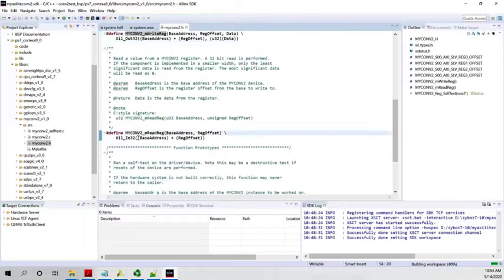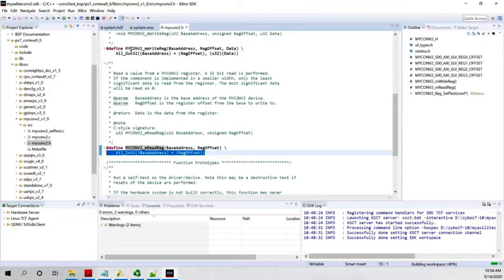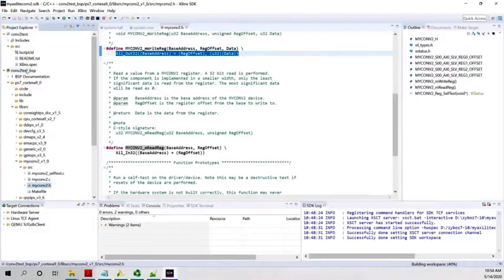The same, right? You read the base address, that's an offset, of course. Remember, this is just this simple XIL function, which is I think one of the most basic functions in the kernel, to read and write. Okay, so if you want, you can just forget about this, right, and just use this XIL in and XIL out for everything. You can do that as well. Let me see if this thing has completed. Not yet. Just gotta give it a little bit more time.